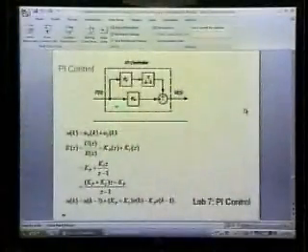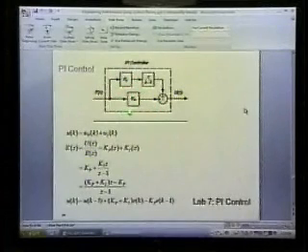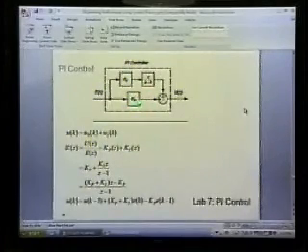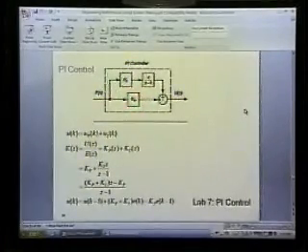So if you think of this, it's really two controllers in parallel. You've got a Kp and a Ki. This is for the integral controller, and this is for the proportional controller. By having two constants here, you get more flexibility about how fast you want it versus how smooth you want it. And that's the advantage. It'll be accurate because of the integral part; anything with an integral controller will have the accuracy property. But then you've got this fast versus smooth trade-off, and you get more control, more opportunity there with the Ki and the Kp, and also the overshoot.